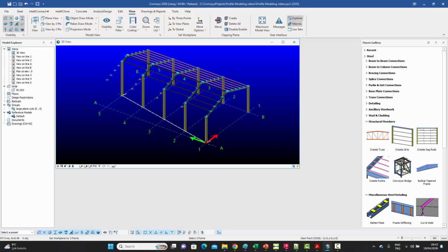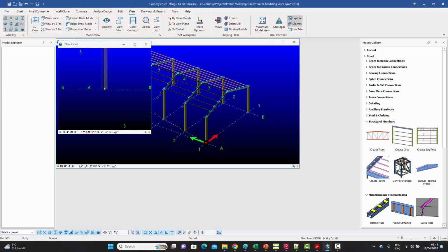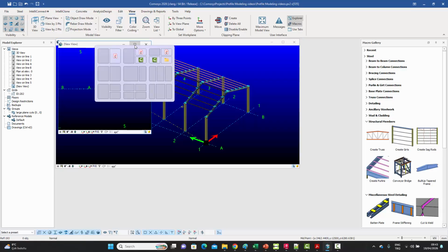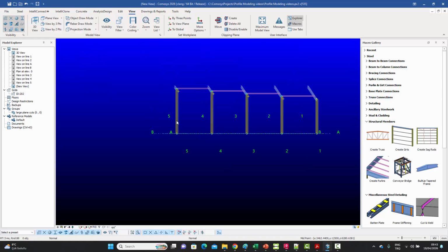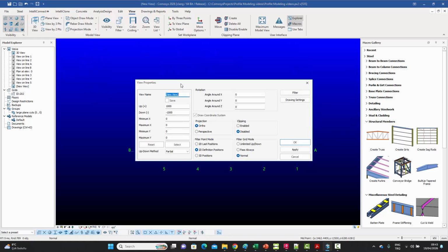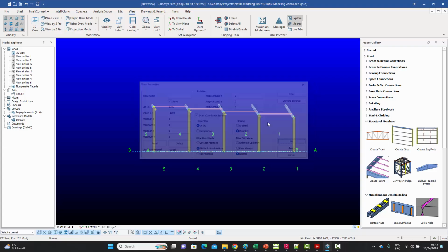And now you can see those little arrows at the end. They're pointing in the direction which is perpendicular to that non-parallel facade. And when I click on that, I create this new view. And a good idea is to actually immediately give this view a name. Let's give it a name of non-parallel facade, like by double-clicking on it.